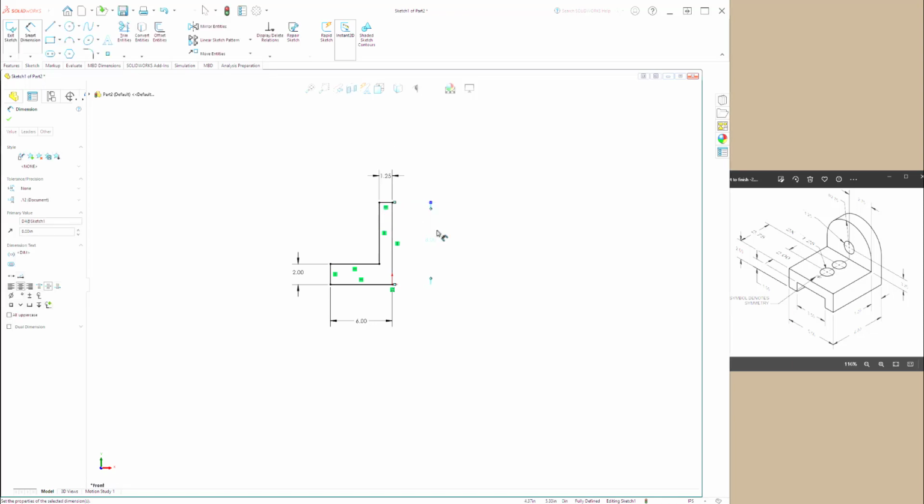So sometimes you have to go and add the dimensions up to get the overall height. So now that we have the dimensions set, notice that there are no blue lines left. All the lines have turned the dark color, and that means that it is configured and constrained properly. So from here, we're done with our basic sketch.